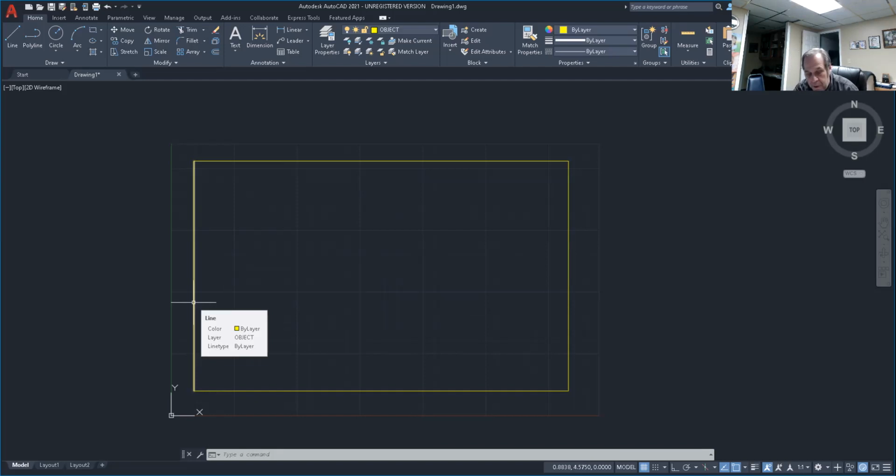Now, if you look at the drawing that I gave you, remember, we're doing the guide block, okay? What we need to do is draw the front view, the top view, and the right side view. Now, there's a couple of assignments that I will give to you, and I'll post those in the files tab to kind of help you out with this, but I want to just get going here. So our front view is going to be right in this area. Our top view is going to be right above it, and our right side view is going to be directly to the right of the front view. So our right side view will be right here.